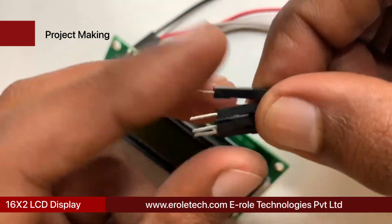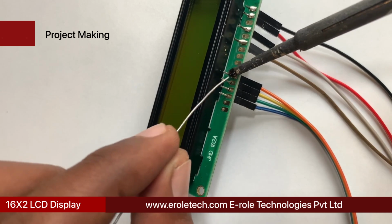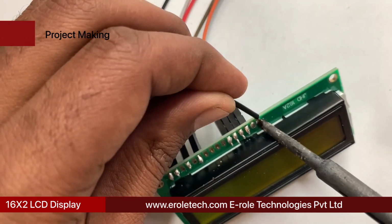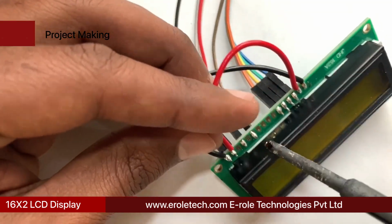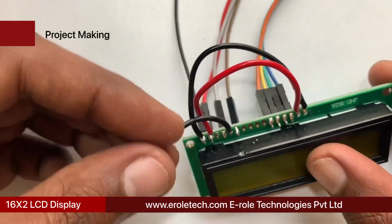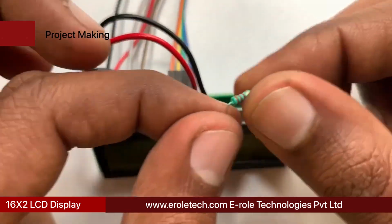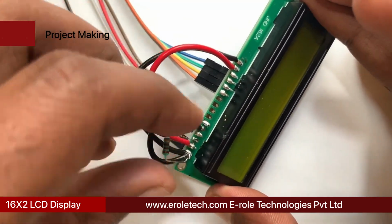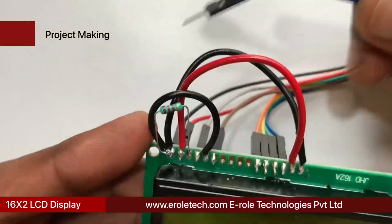Now we will solder orange, yellow, green, and blue wires at pin number 11, 12, 13, and 14 of LCD display. Now connect hole number 16 with hole number 1 using a black wire, and hole number 15 with hole number 2 of LCD display using a red wire. Now connect hole number 5 with hole number 1 using a black wire. Now connect hole number 3 with hole number 1 through a 1 kilo ohm resistor.